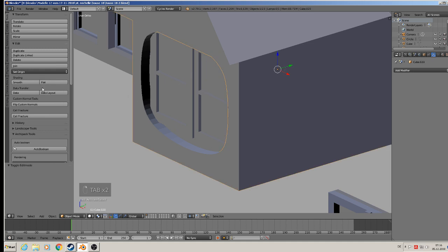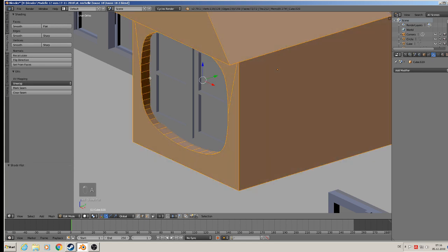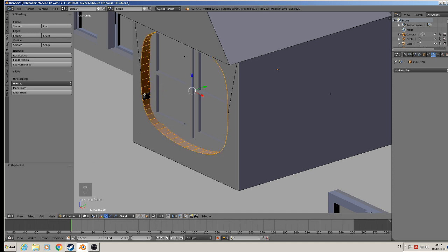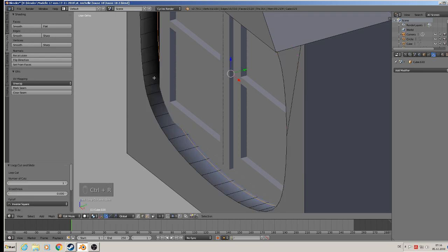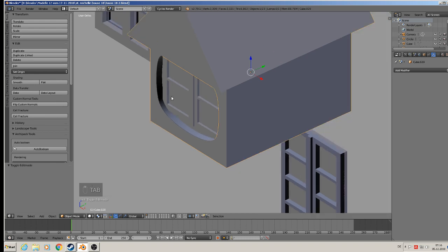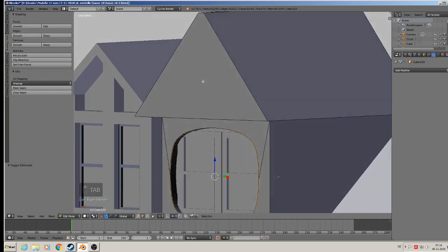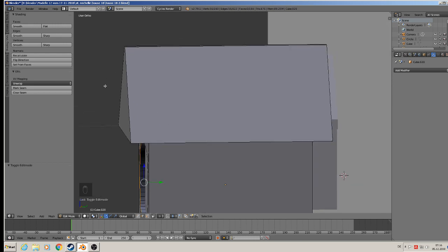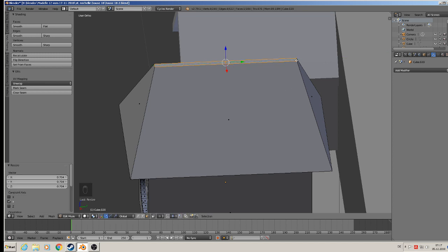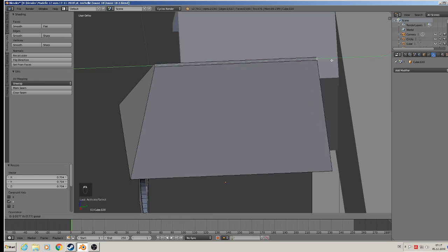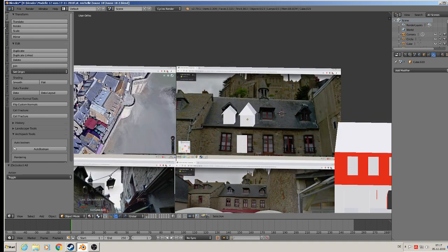Good, here we need a smooth on. You see it here on these faces, but we don't smooth anything. We only smooth that inner ring here. So smooth. Then we need here 2 loops to get the shading errors away. There's one there, Control R, one there, and shading errors are gone. Good. That is fine, but I think we get a little leaning here is better. So we take that and scale Y, switch like that maybe. Sure, that can be straight, but here the front should be a little bit leaned, I think. So, okay, we have that. File, save.